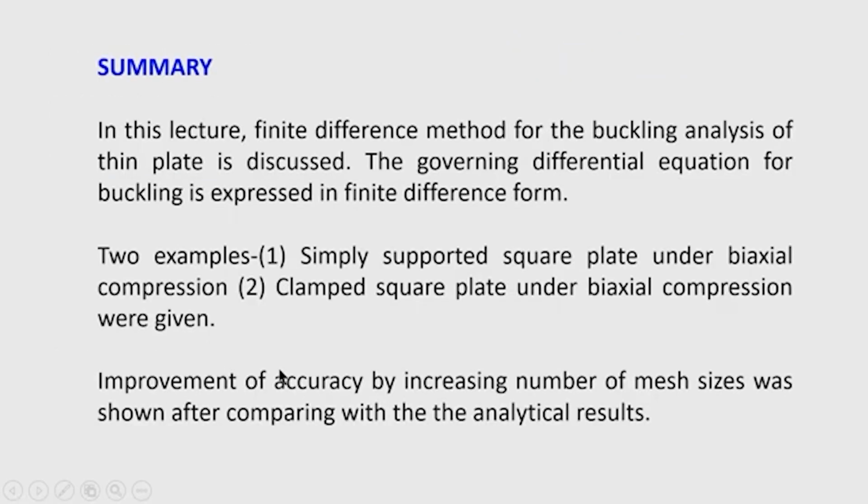Okay. So, let us summarize what we have done in today's lecture. In this lecture, the finite difference method for buckling analysis of thin plates is discussed. The governing differential equation for buckling is expressed in finite difference form first, and then we use this finite difference equation in solving two problems.